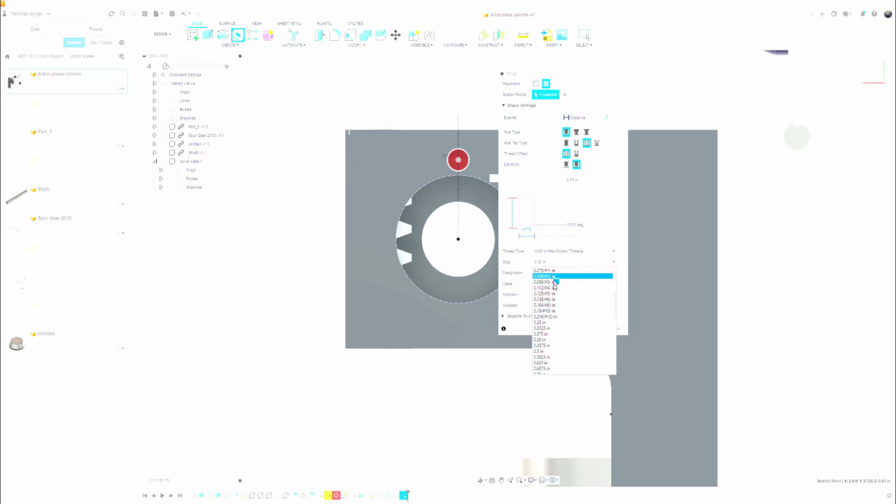So what we have to do is find a number 8 screw, which in this case is a 0.164. Remember, the through hole on the cover plate is 0.172, so it's larger. It gives that little bit of play to thread that screw into the threaded hole here. So this is a number 8. That's where the 8-32 comes into play. So let's select number 8. And you'll see that 8-32 is the default designation. There is an 8-36 also. So this is an 8-32.